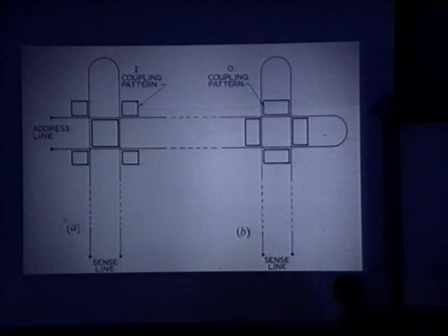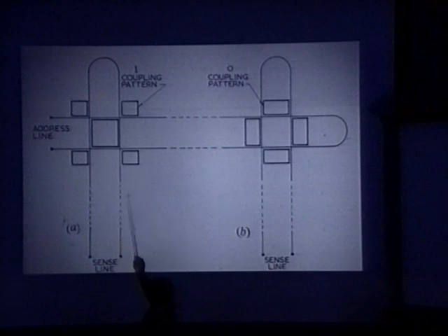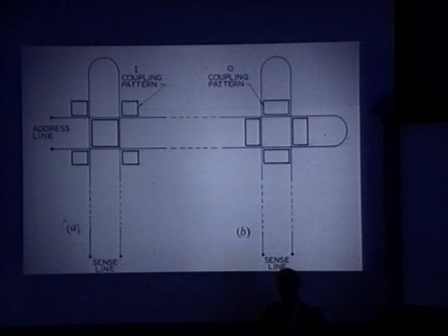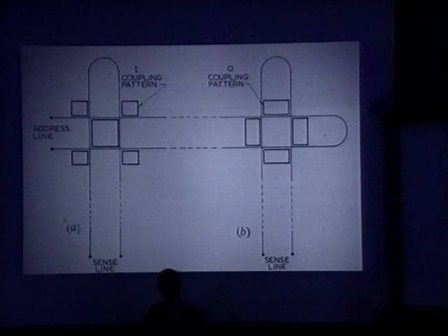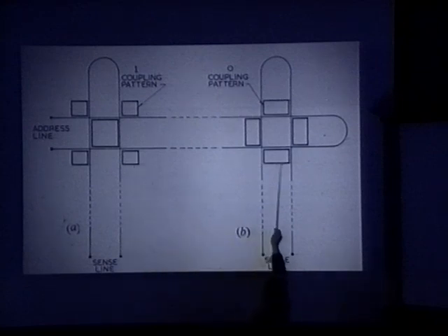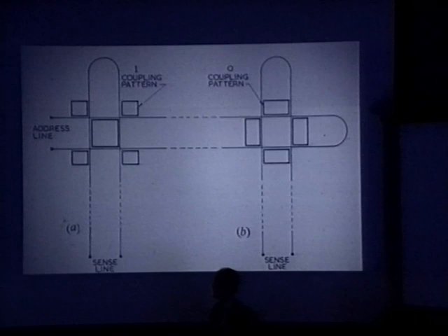Like Kilburn's array, we have a balanced system with pairs of address lines and pairs of sense lines, printed circuits, not a woven matrix. And in place of the ferrite rods, 2 patterns etched on a copper sheet, on a board with a copper sheet on it. And there was the X pattern and the 0 pattern, hence the noughts and crosses.